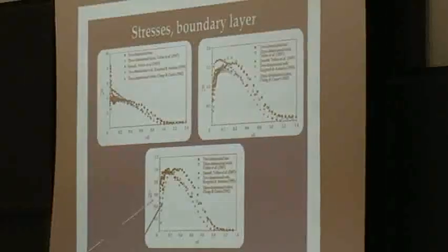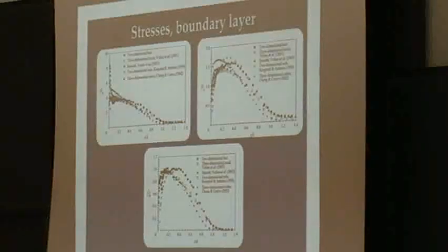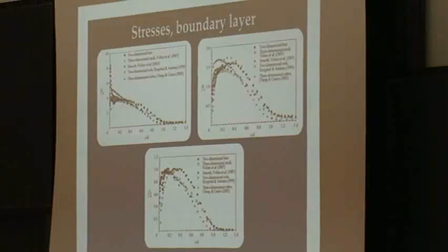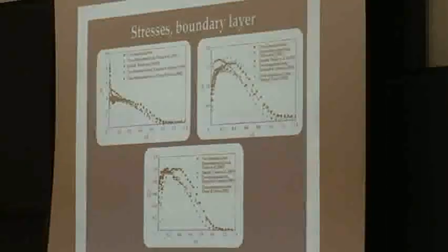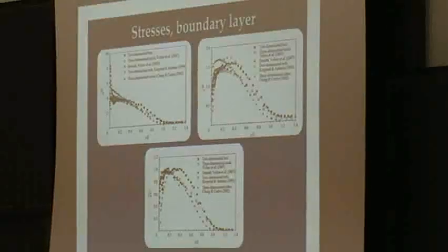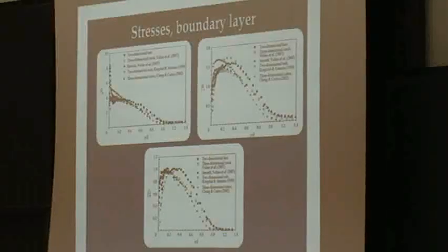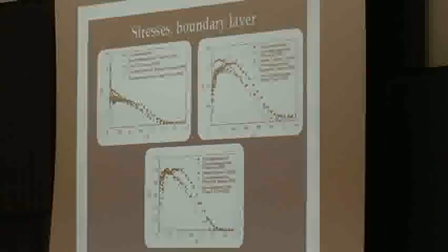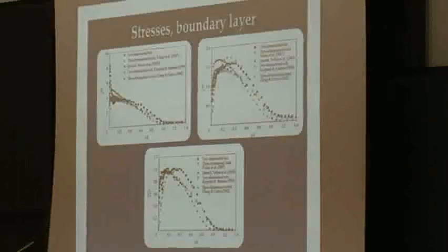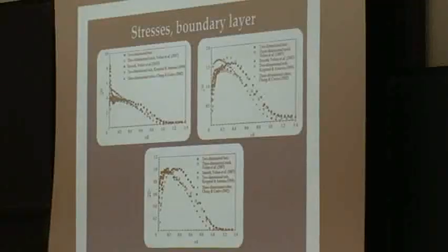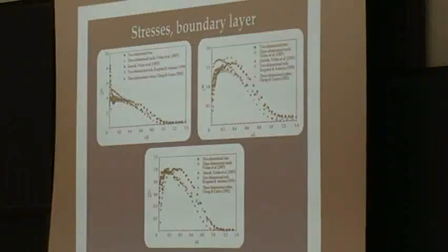Or could it be that the two-dimensional roughness acts differently, like we thought it would do when we designed our rough wall experiment? Or could it be that the outer layer effect is due to the differences in outer boundary conditions? Because in the channel flow we have a symmetry line at the center line, so therefore the outer boundary condition is more rigid than in the case of a boundary layer.